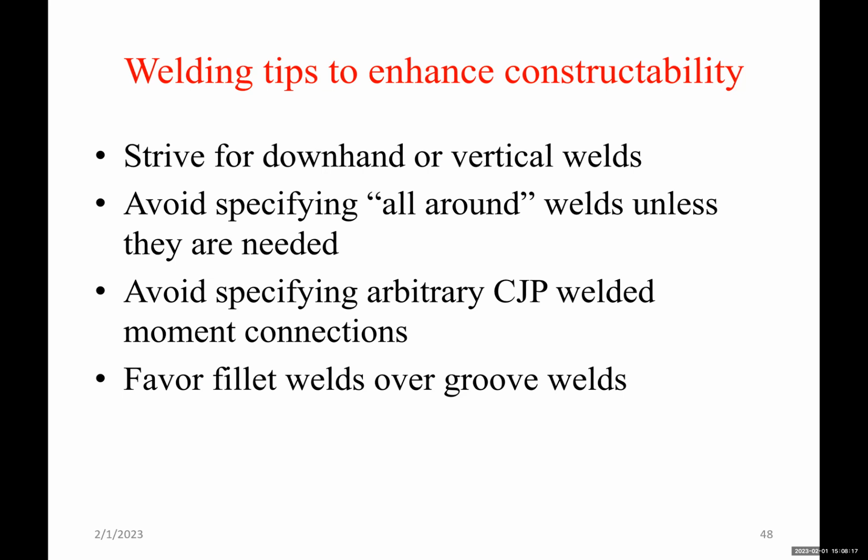We have a question here. Are we supposed to specify coping dimensions? Yes. You would know what's needed to fit a beam inside the web of the column, let's say, or a beam into a girder. So you know what the flange width is that is conflicting with the top flange of the beam.